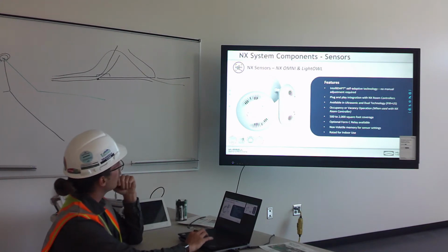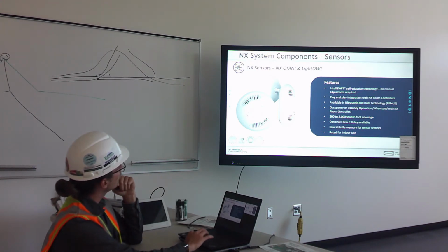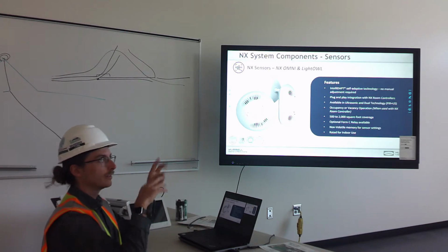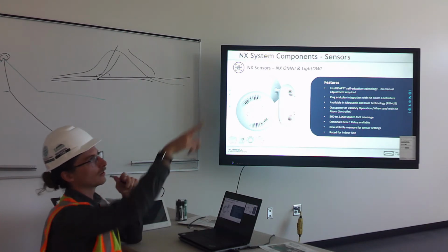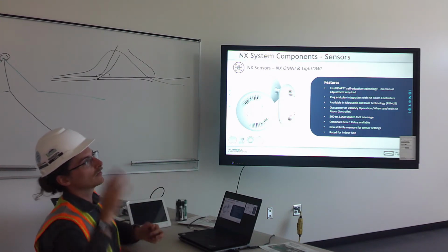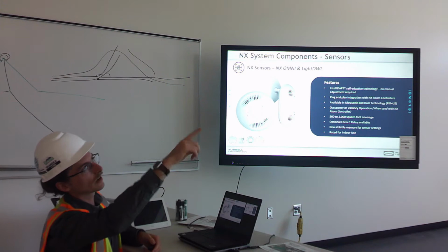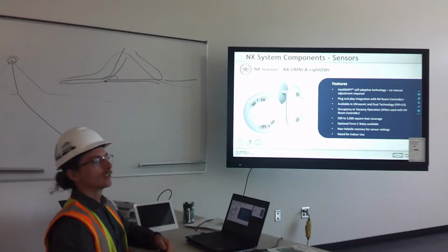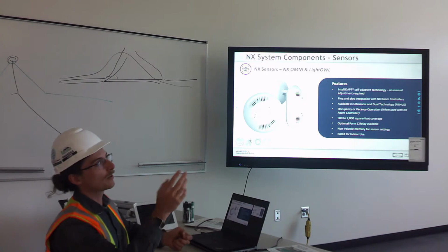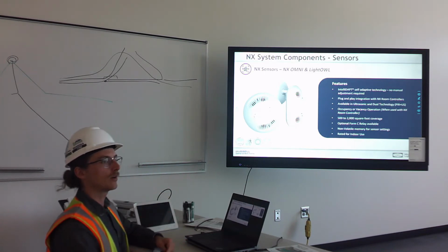Each of these has a green light in that little lens piece, and a red light behind this lens, and those light up when each individual sensor is picking you up. On that one it might be a little too bright to see easily, but if you wave your arm, you should see that green light turn on. That's a quick troubleshooting thing to see if the sensor even has power, if it's picking you up, and what's going on with it.